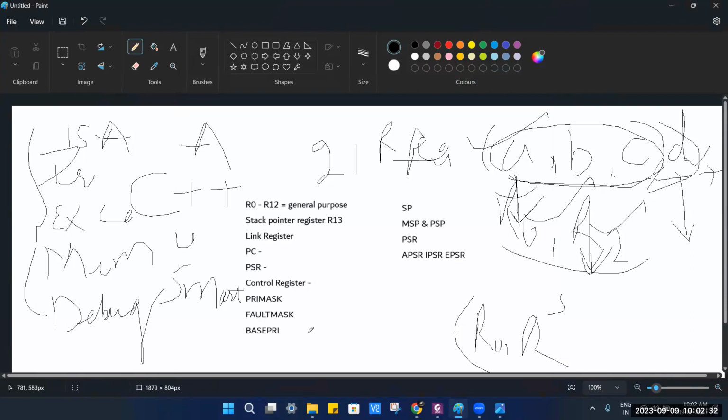Okay. So you are saying one program is a bootloader and you have application firmware, right? Both are flashed in different memory locations as required, and you have to debug both of them. It is flashed in bin format. It is not an ELF file. So how will you check whether it is hitting the application program properly during the debug session? How will I do this?